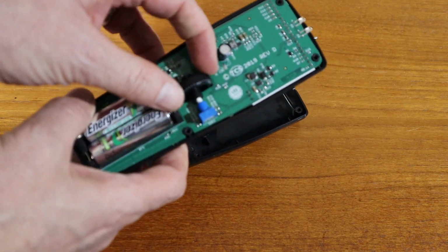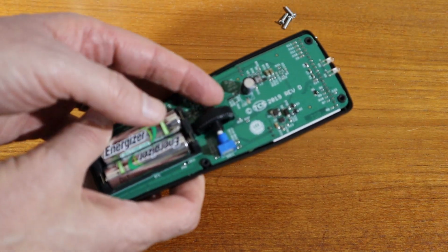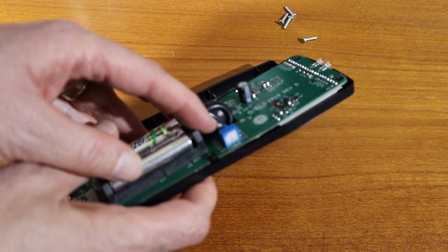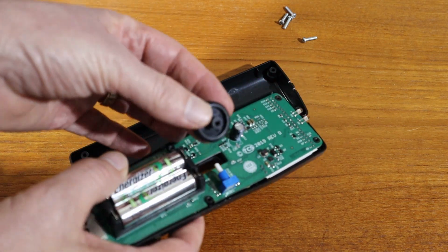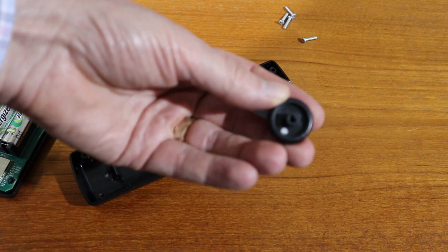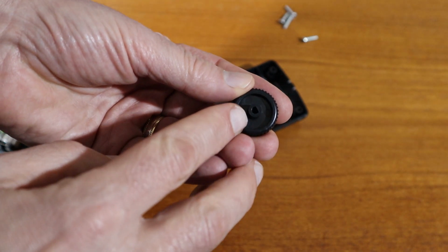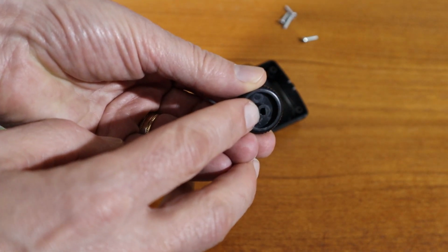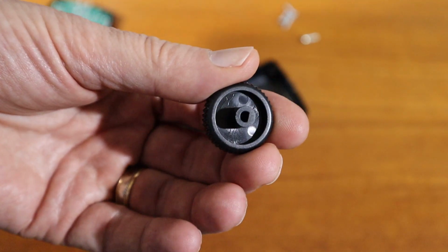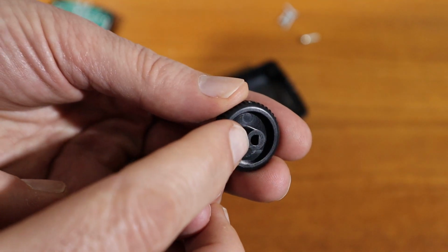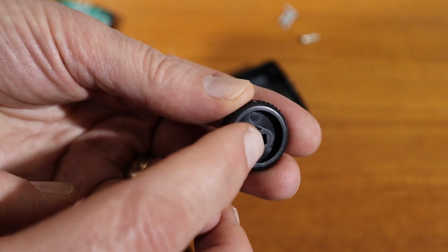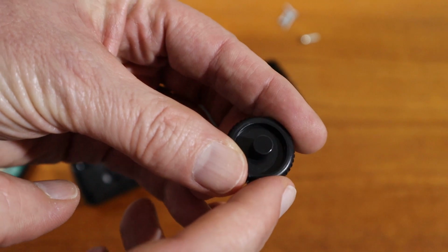Another thing is, if you look right now, you can see that this thumb wheel is very loose. The reason it's very loose is because we used what's known as a steel-safe design. So in a steel-safe design, the mold can be modified to give a better fit by removing steel. Let me get the focus correct. So this hole here is a D-shaped hole. Let me see if I can get closer. This D-shaped hole is larger than it needs to be, and that way they can slowly remove steel from the mold until it's a very slight slip fit over the shaft of the encoder.